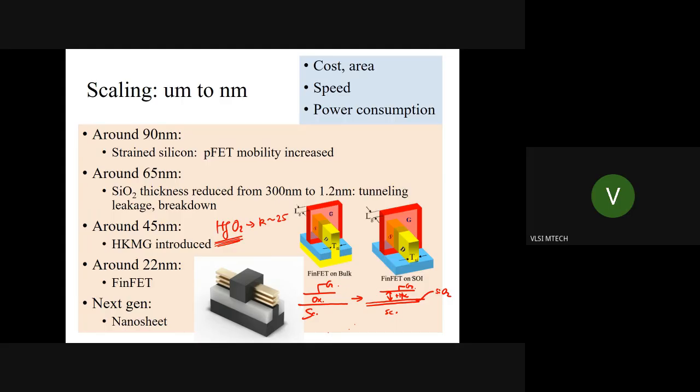Okay, so if I have to have a lot of electric fields from the gate reach the channel, then I can do away with a thicker high K material as compared to silicon. So if I have a silicon and high K of the same thickness, not a lot of field will go into the channel through this. High K will allow a lot of field to go into the channel. So this thick high K is equivalent to a very thin SiO2.